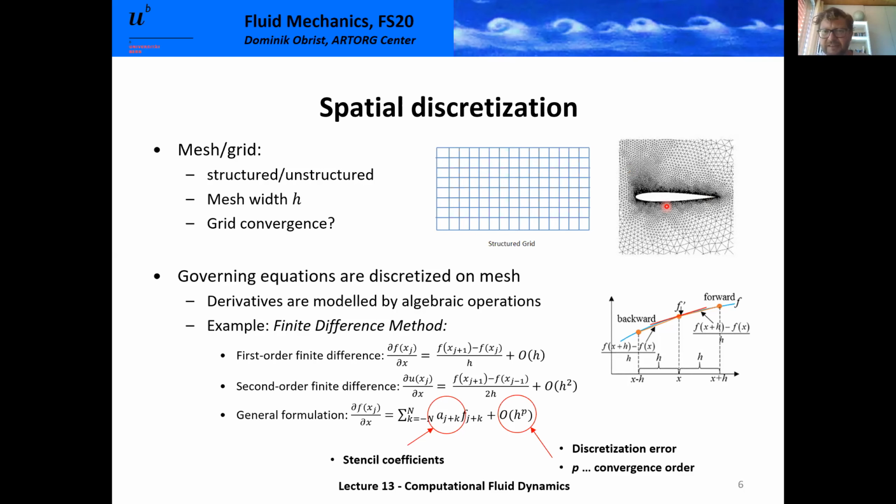Okay, so let's say we have selected one of these grids. So what's the next step? Next step is discretization. And usually, or in many cases, the CFD code does that for you. But very often you will have to, at least by a click on certain buttons, select which scheme is used to discretize that. There are many schemes, and I have 2 slides to explain that. But let me just show you on one example what such a scheme could look like.